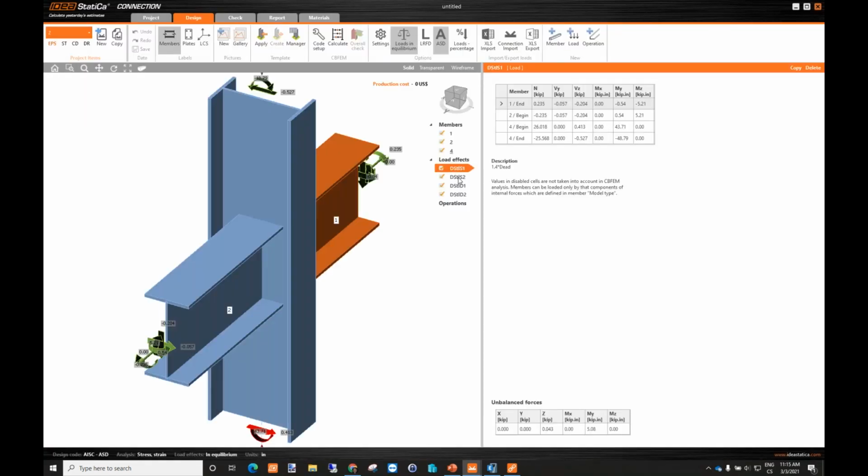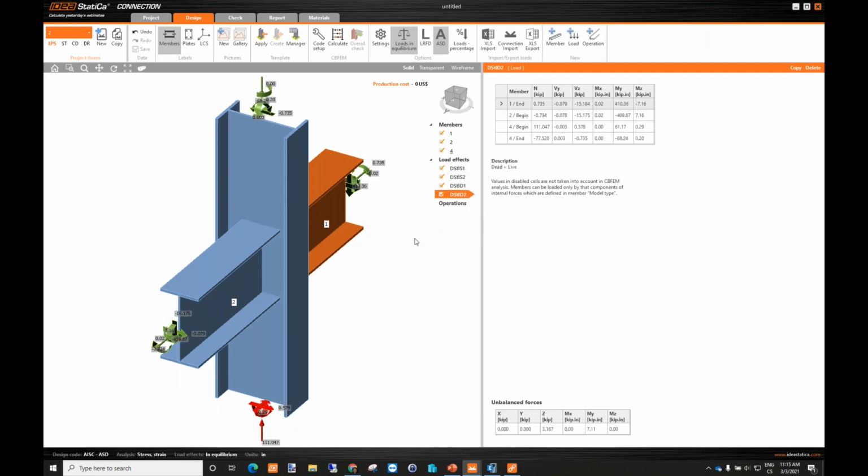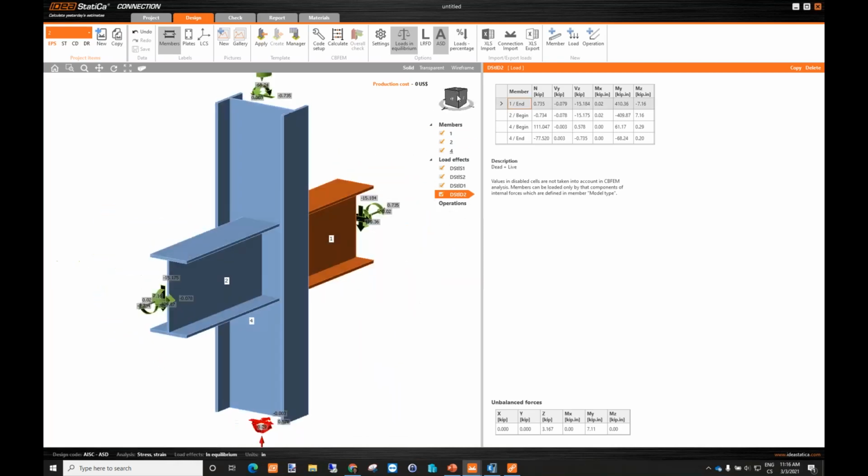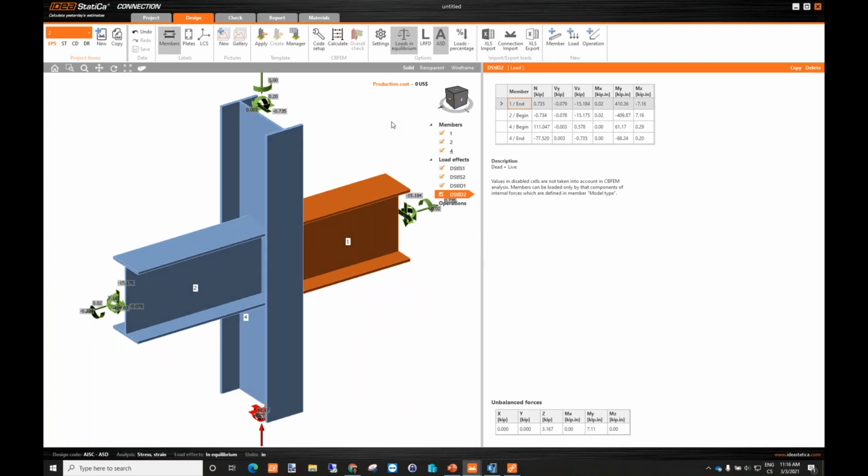And you can see we have already the items here. So in this case, we used the synchronizing button to upload the correct loads. And of course, you can do it also with the members. If you have, for example, if you change the height of the member, again, go to ETABS, change it there, make the analysis again, and go back, click on the button synchronize, and the changes will be imported into IDEA StatiCa.